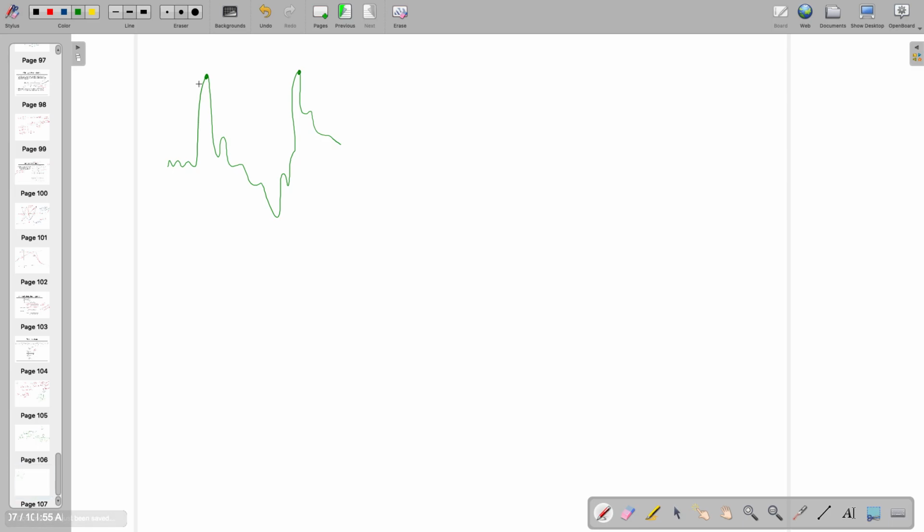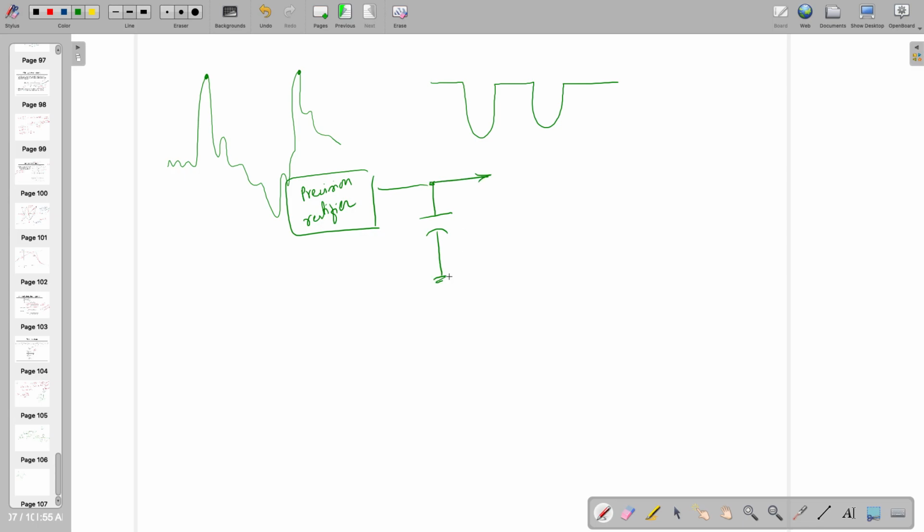You can do that, but just now we have made something where it is giving such output. Reverse of that means reverse bias diode, and at the output add a big capacitor with precision rectifier. Just keep a big capacitor. So in positive and negative, any side you can do that, and your output will look like this. So you have to take care of the RC time constant.